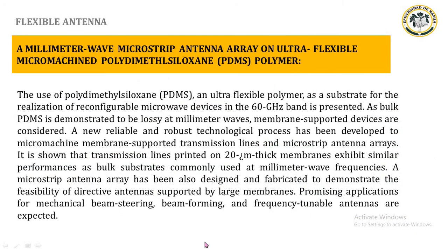A millimeter wave microstrip antenna array on ultra-flexible micromachined polydimethylsiloxane, or PDMS, polymer. The use of PDMS, an ultra-flexible polymer, as a substrate for the realization of reconfigurable microwave devices in the 60 GHz band is presented. As bulk, PDMS is demonstrated to be lossy at millimeter waves.